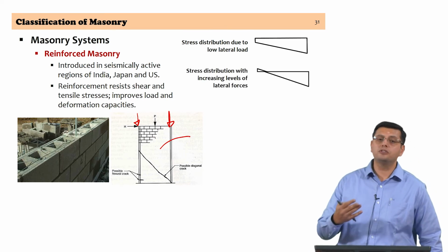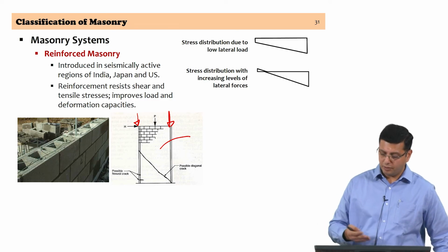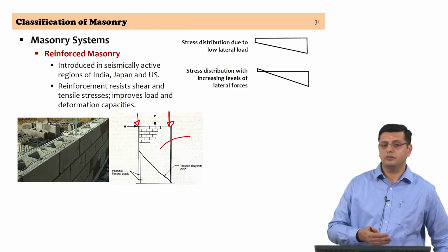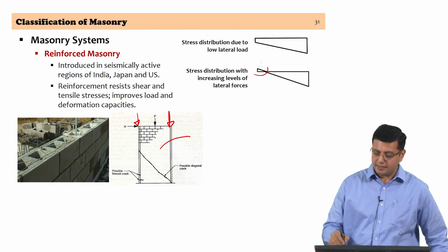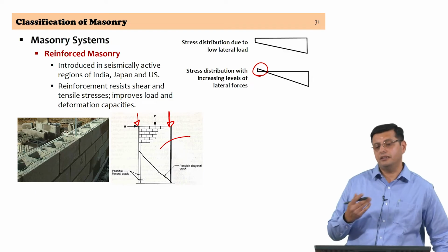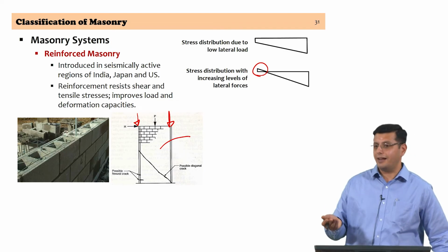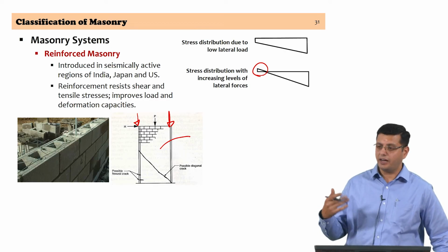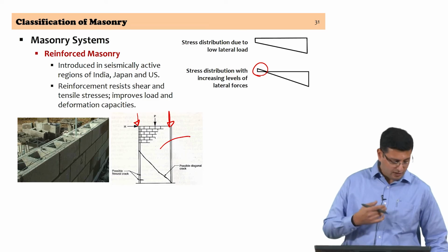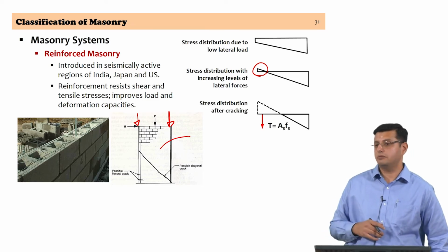The design loads might themselves take the wall into cracking because of tension. The masonry wall might have some finite tensile strength, and if the case is so, the masonry need not crack. You have the entire cross section still active for gravity and for lateral forces. This again need not be the case.